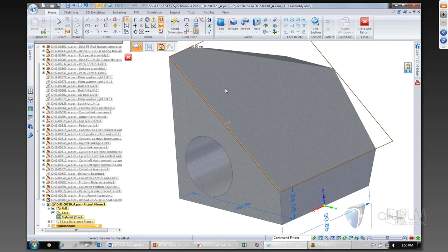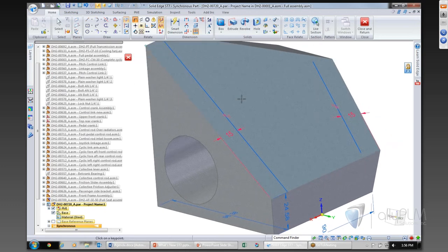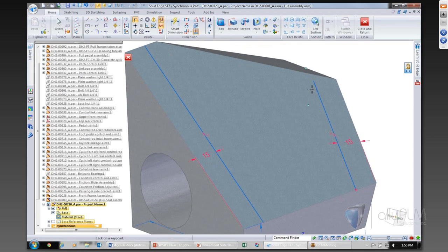So in many cases, such as this one, it may be quicker and easier to create a shape of a complex component as a Solid Edge part initially, and then convert that into a sheet metal part later. Determining where the bends should be placed and at what angles can be hard sometimes. So by creating it as a block first, we can reduce the complexity of building this part directly as sheet metal. You'll notice as we sketch, the great graphical feedback we now get.